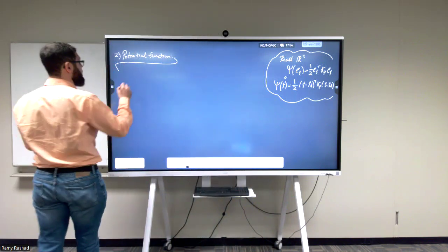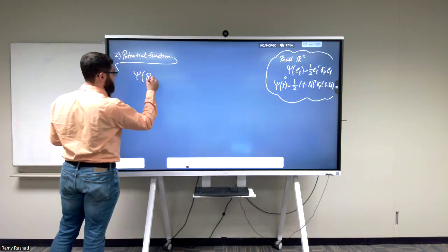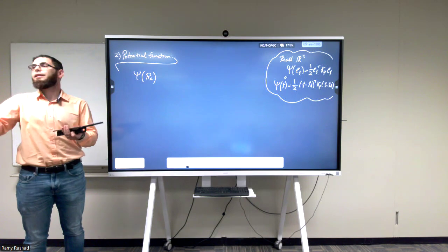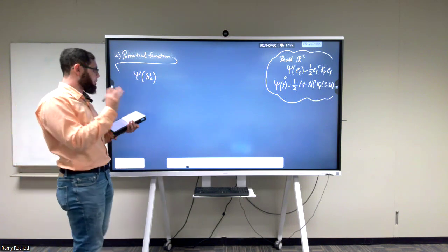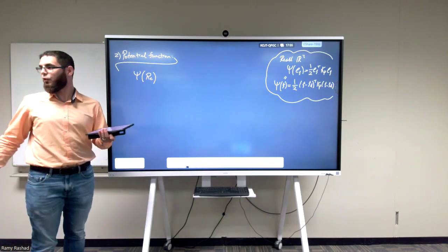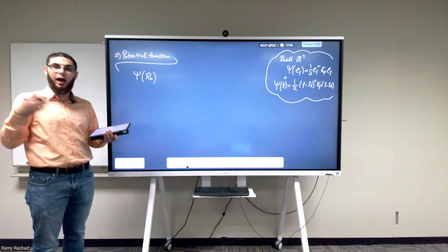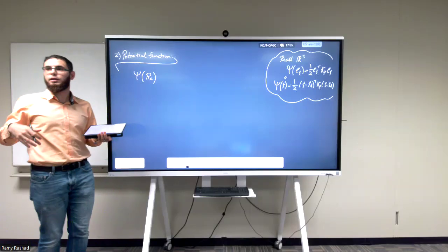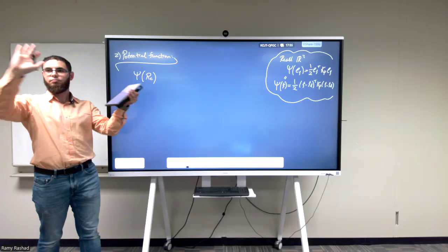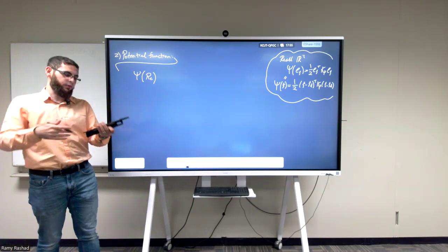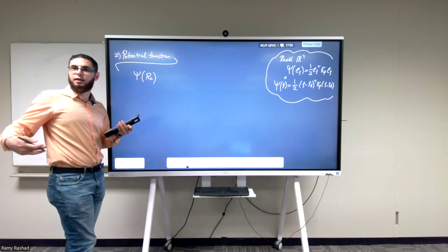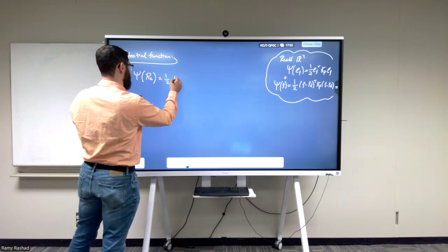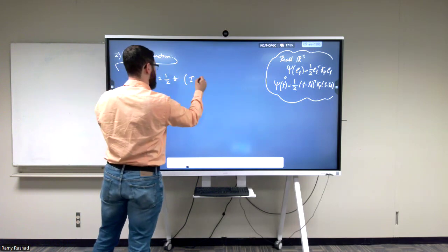Now let's look at the potential function we're going to be writing as a function of R_E. We want something that will have a minimum when R_E is identity. I'm going to say what the function is and derive everything for it, and if we have some time in the end, I can tell you how you can actually come up with it the other way around. But it's much easier to follow the line of thought, because you're seeing this for the first time, to have it given like that. I'm not going to motivate where it comes from, but you're going to see, when it's derived, that it does exactly what we want. So this potential function is half the trace of the identity minus R_E.